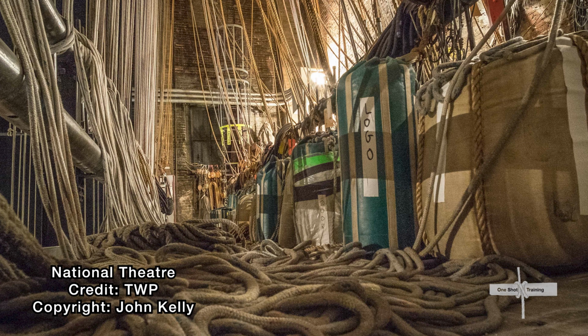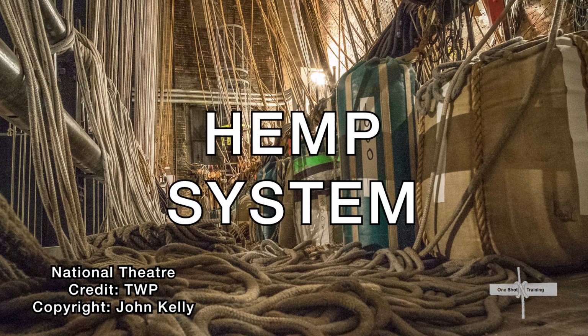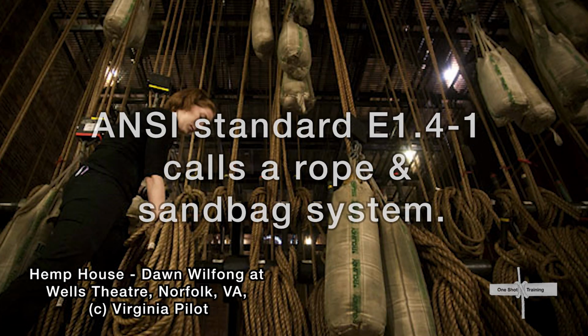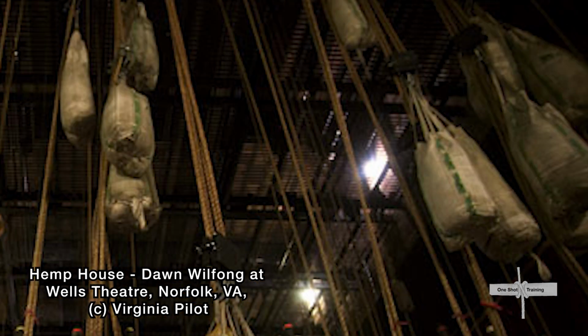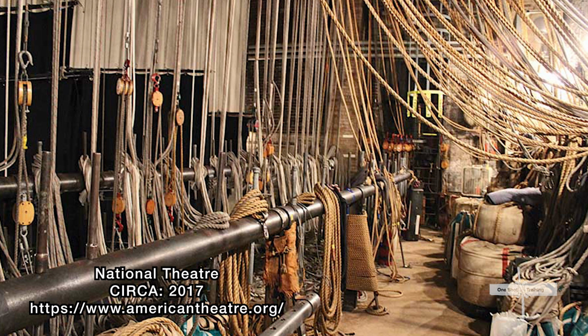The oldest version of stage rigging systems is called the hemp system, which the ANSI standard E1.4-1 calls a rope and sandbag system. It is a traditional rigging system where all loads are hung on a rope that is counterbalanced with a sandbag, or other weights attached to that same rope via a trim clamp, or what we call a Sunday. There are not many theaters left today that use this system, but the techniques are sometimes used in a theater or other space for some specific tasks that the counterweight system or other pre-existing systems do not easily accommodate.